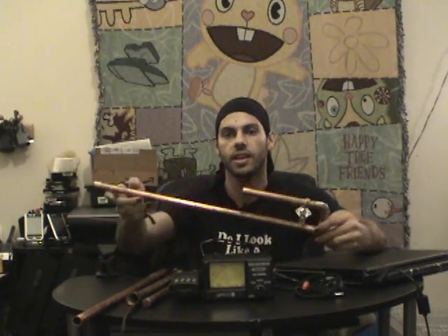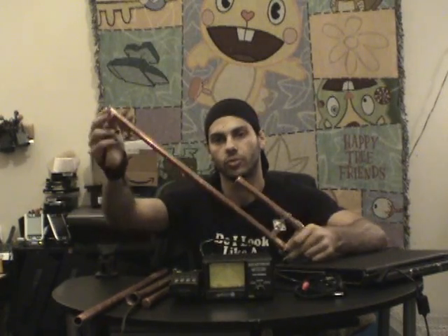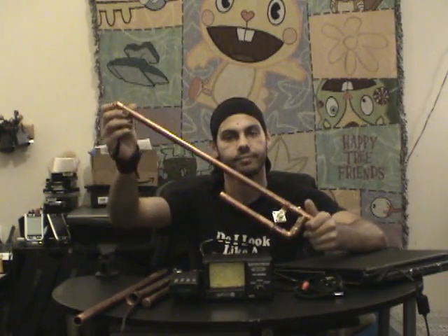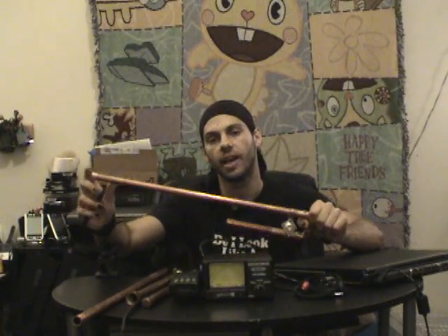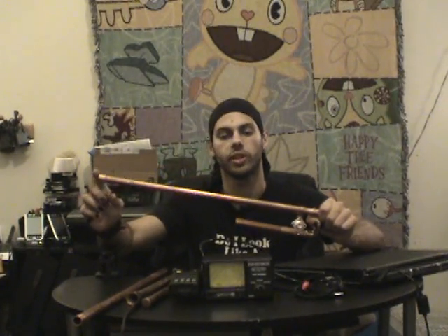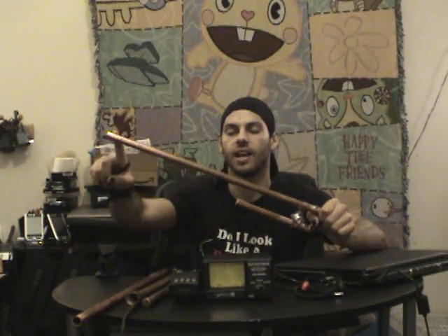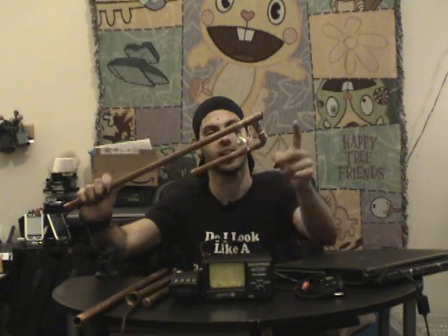Now, a J-pole antenna looks like a big letter J. Now, this is actually a half-wave dipole. It's just kind of bent and contorted. Now, this side is actually half wavelength, and then this is 1/4 wavelength, as well as this side is 1/4 wavelength. Now, the gap between it, all of this, with any antenna has to be mathematically calculated.